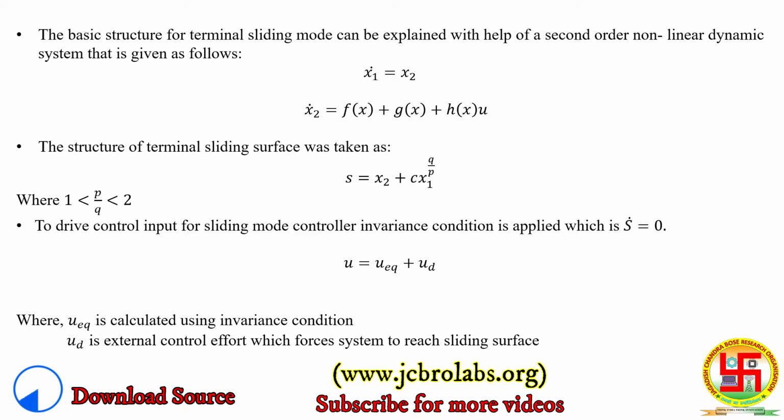The basic structure of terminal sliding mode control technique has been explained here, where a second order non-linear system is taken where x1 dot is equal to x2 and x2 dot is a function of system states as well as u, that is control input.